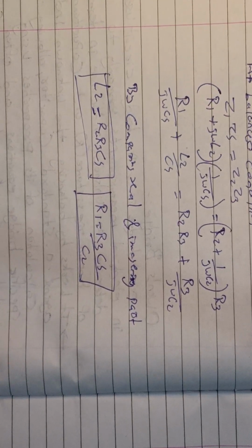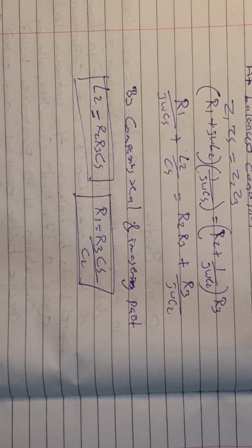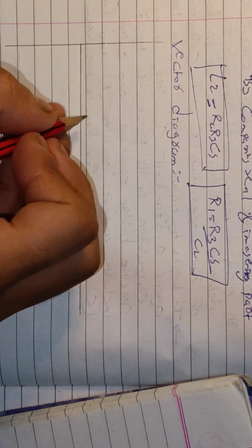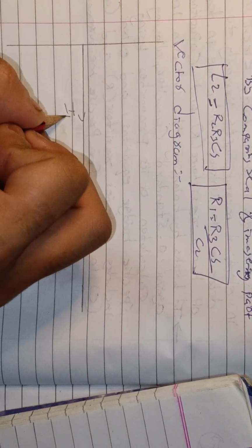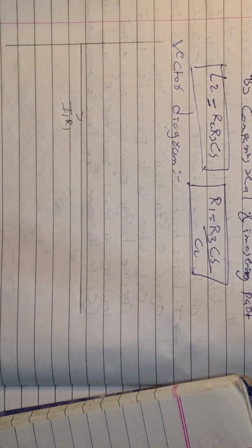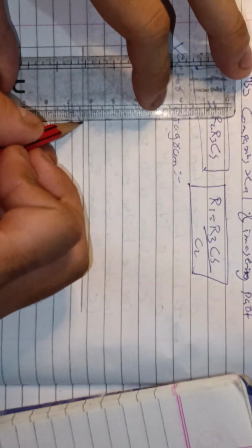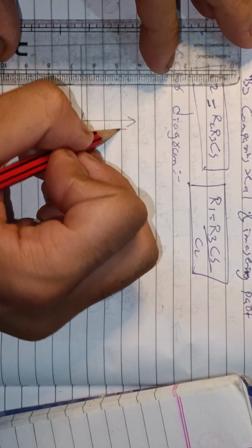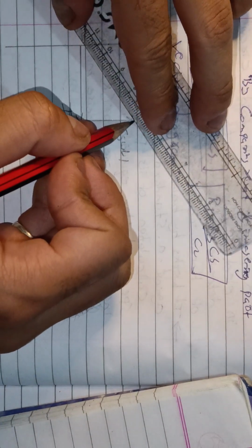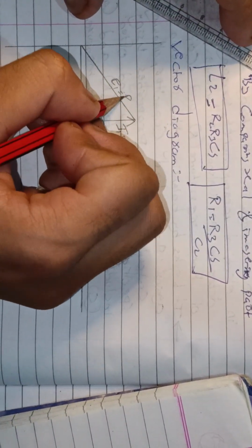Now we'll see the vector diagram. I1 R1 drop will be on the x-axis. Because of the inductance, I1 times j omega L1 will be 90 degrees leading on the y-axis. Together we will get E1. E1 and E2 are both equal in value.